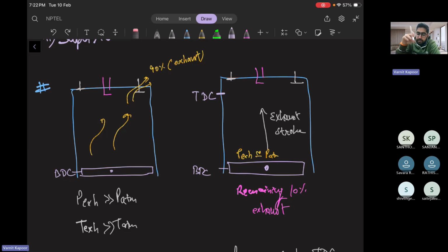Basically these valves operate on a camshaft with a spring loaded mechanism, through a timing chain. From the crankshaft, the chain is connected to gears and a camshaft assembly, because of which the spring is pushed down during the exhaust, and for most of the time it is closed. That is why the time of closing of the exhaust valve is more compared to the opening.